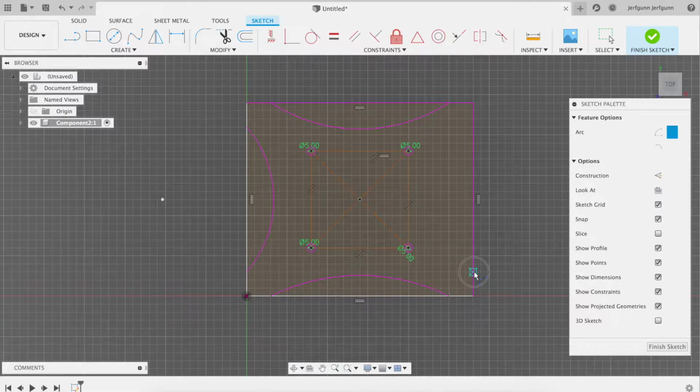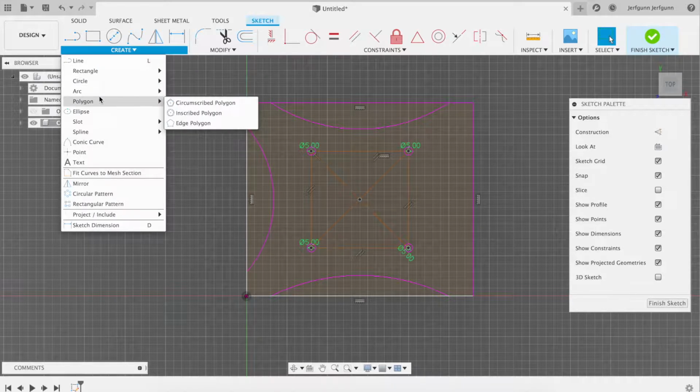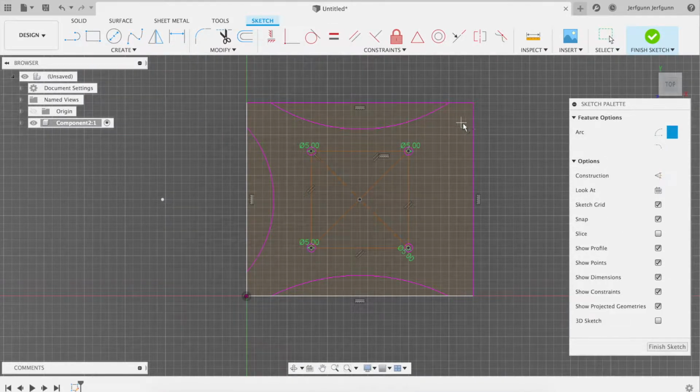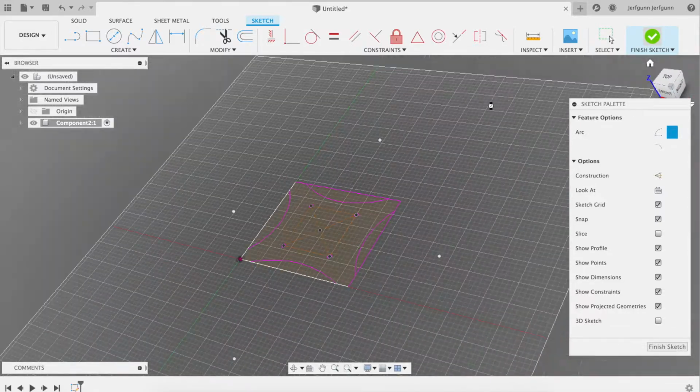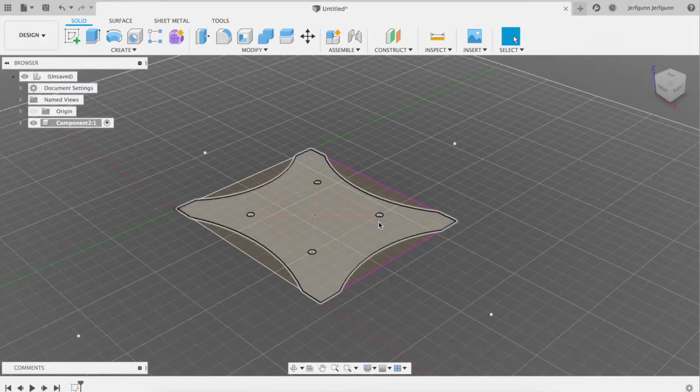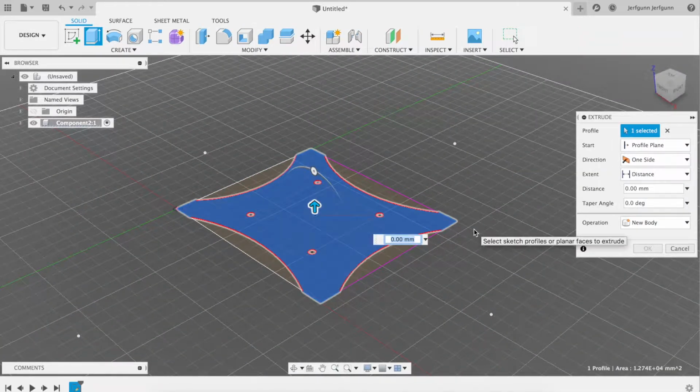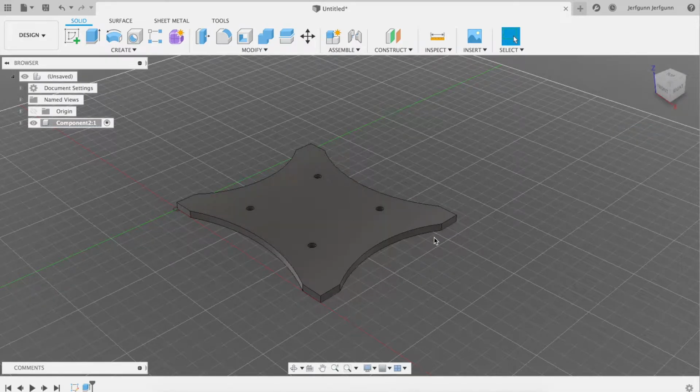Hopefully, you guys watching this example later on, you're not going to get too upset about that. Okay, so I've got all of these features. I hit Finish Sketch. And then I go in and I extrude, and in this case, with one extrude operation, because I started with that base sketch, I've got a part shaped like this. And maybe that's what I'm going for.